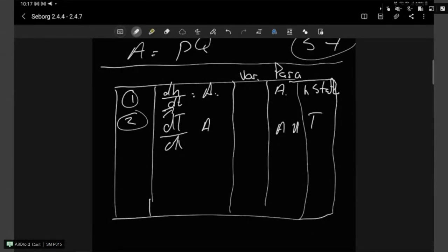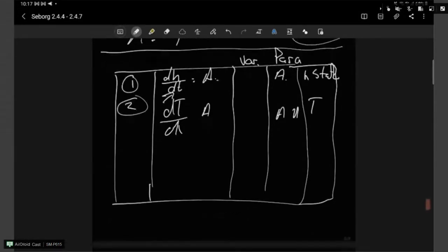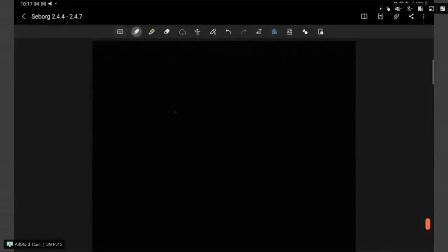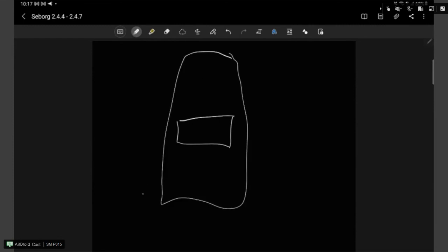And specifically for stage systems, always remember that you need to do a balance on a stage. Obviously you can do it over the entire vessel, you will do your complete mass and component balance, but you need to determine the changes in the vapor and liquid per stage.